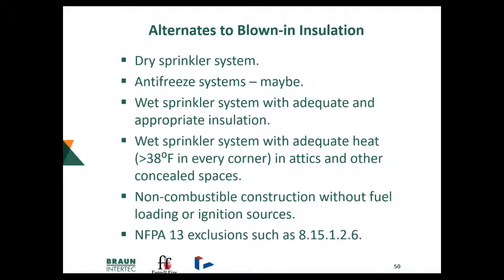Antifreeze systems are costly. They're costly to install. They're very costly to maintain. They have to be verified annually, and often they have to have the antifreeze replaced. And then we also have the problem that antifreeze systems for temperatures in Minnesota, North Dakota, South Dakota, many of the northern tier states have such a concentration of flammable liquids in them that they can contribute to a fire, as was shown in a Fire Protection Research Foundation study that you can get online also if you want to look at it. So antifreeze is not a good option, and it's no longer an option for living spaces.